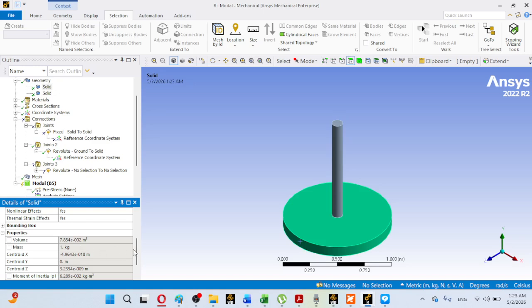You can calculate it here, or you can approximate, show its value here, 0.12412. So this is the ANSYS calculated value, but the true realistic value that you can calculate is 0.125 for this rigid disc, having its radius to be 0.5 and mass of 1 kilogram. So using the formula half m r square, which is the formula for calculation of polar mass moment of inertia.